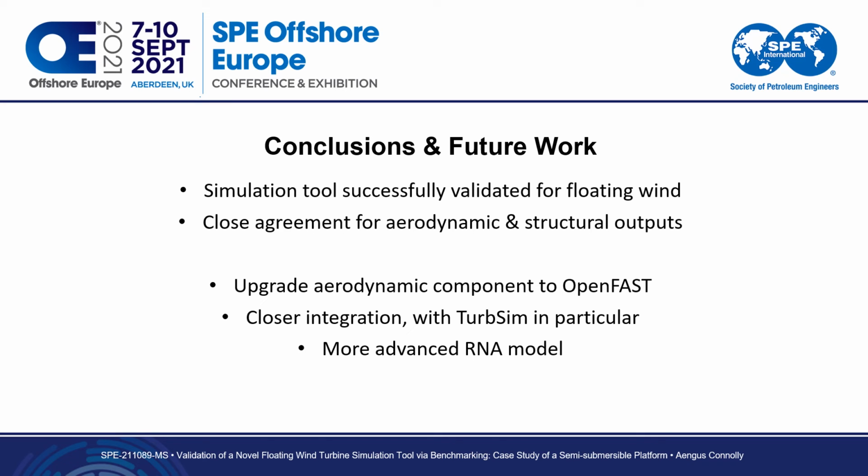So just to summarize briefly the conclusions from the benchmarking exercise and to outline some areas of future work, our simulation software tool has been successfully validated for floating wind applications based on our case study of the DeepCwind semi-submersible platform hosting the OC4 turbine. We've shown very close agreement with the other industry modeling tools in terms of aerodynamic outputs like generator power, rotor speed, and structural outputs like the platform excursions and mooring line tensions and so on. So we're satisfied with the benchmarking exercise.